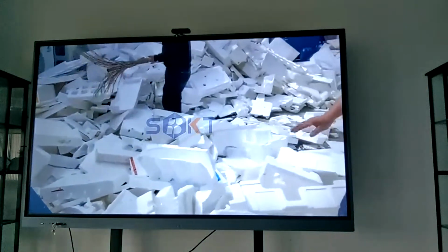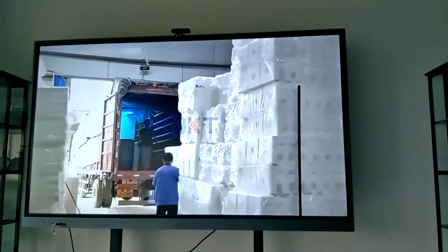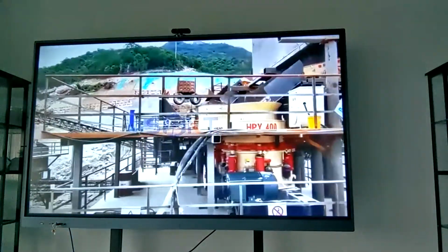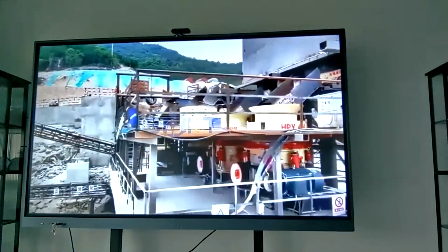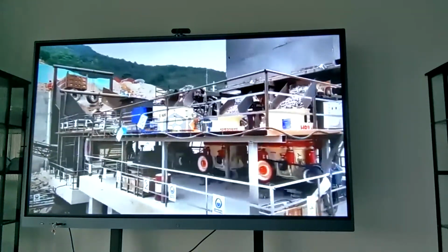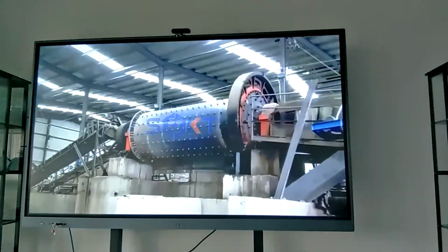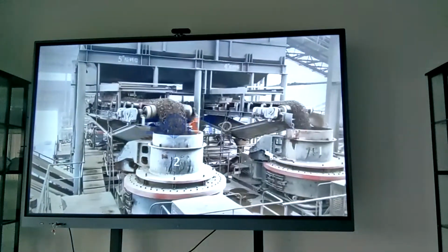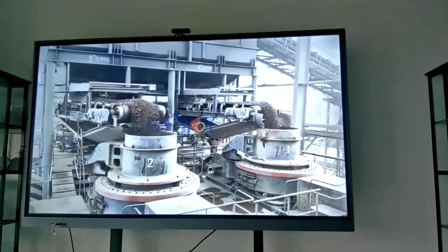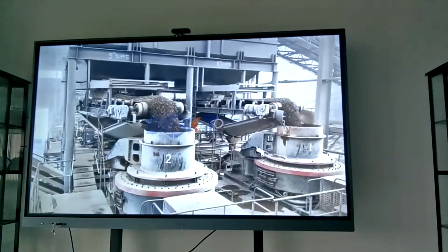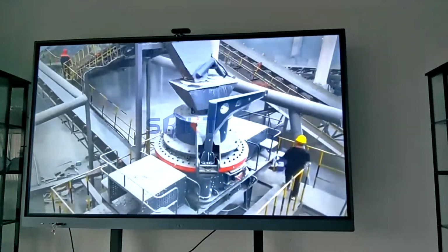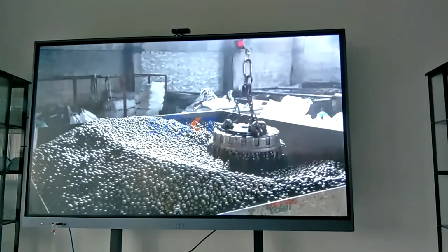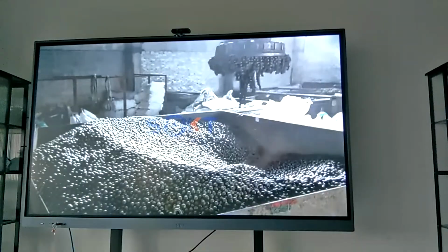Step 2, consider the degree of oxidation and the clay content. Oxidized ore is loose and fractured. If clay content is low and the grade is extremely low, less than 1 gram per ton, use crushing and heap leaching. If clay content is high, still aim for low cost, slightly agglomerate, or use cyanidation for high recovery.